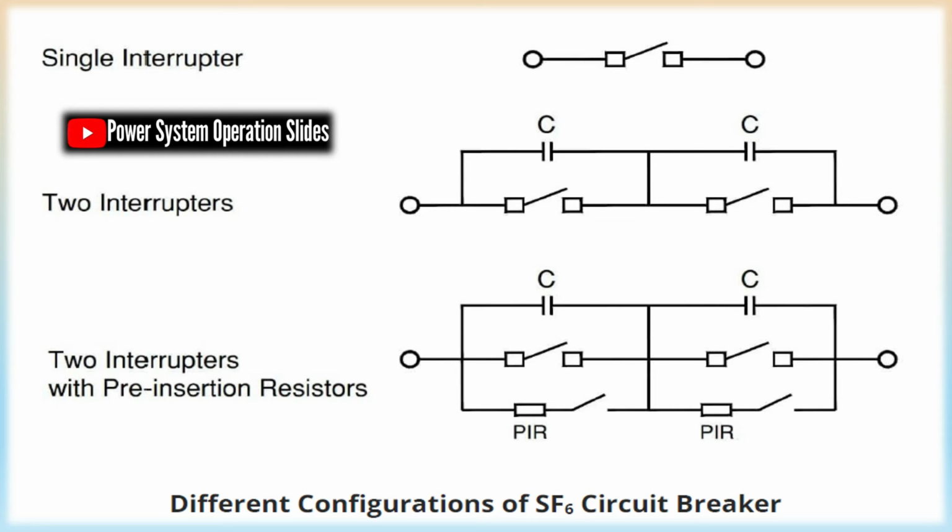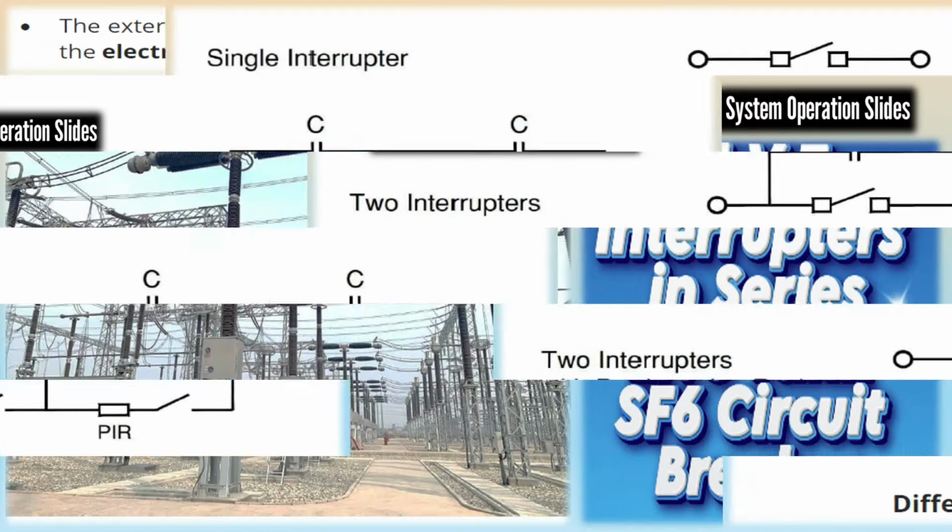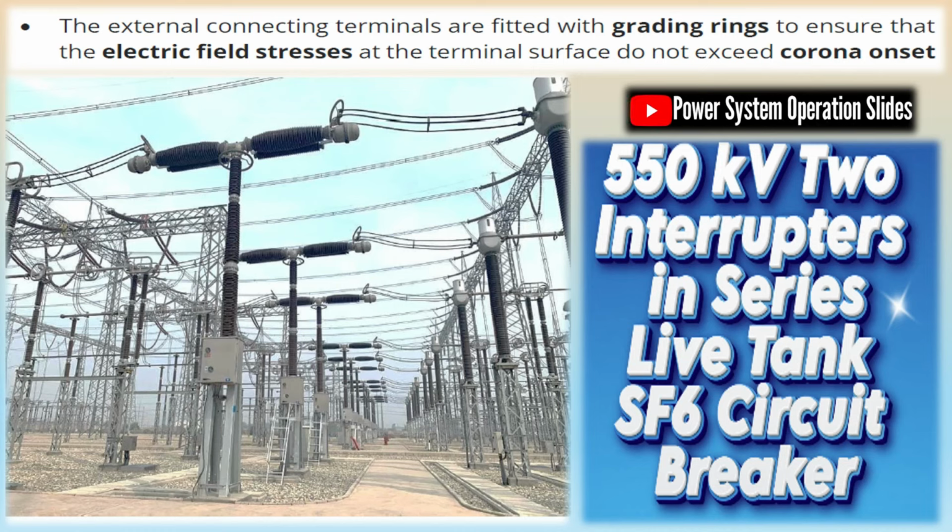When the arc is interrupted, transient recovery voltage starts to appear across the contacts. The opening speed of the circuit breaker contacts should be fast enough to create an adequate contact separation distance to withstand this voltage stress. In case the contact gap's dielectric strength is lower than the TRV stress, the arc will be re-established in a phenomenon which is commonly called circuit breaker reignition or restrike.